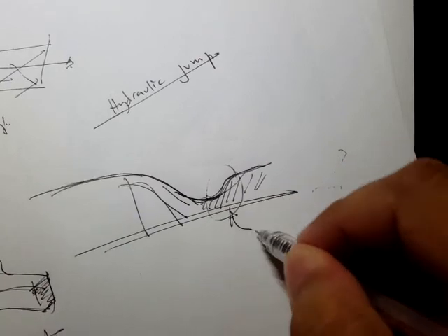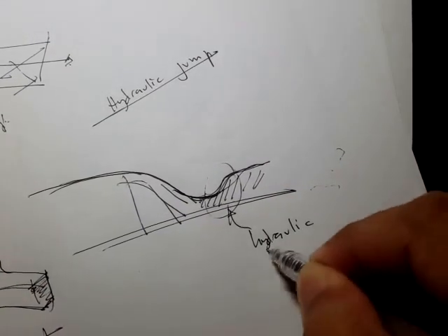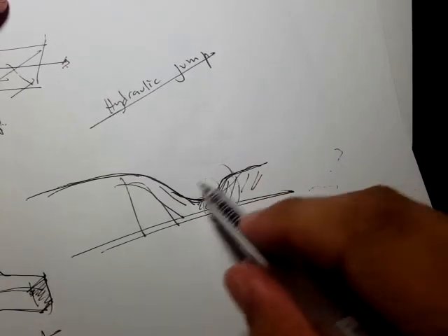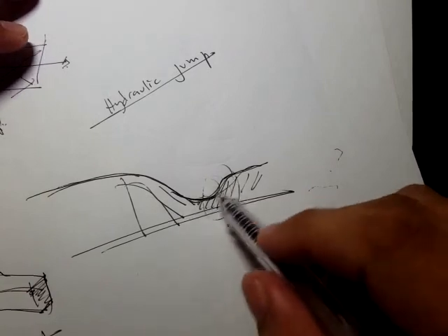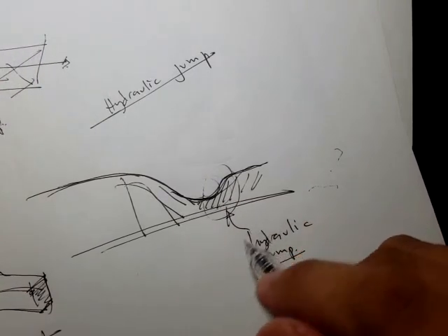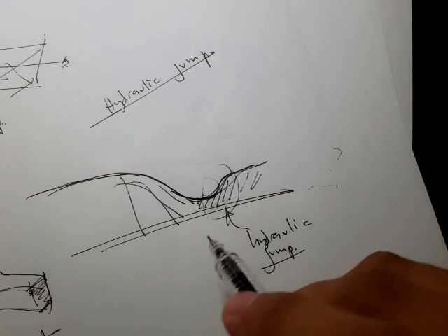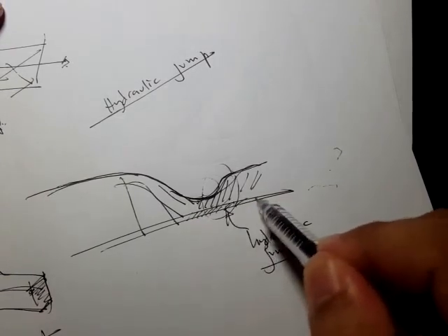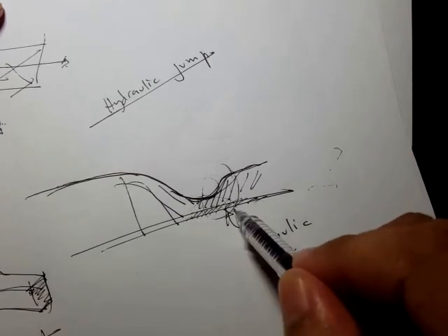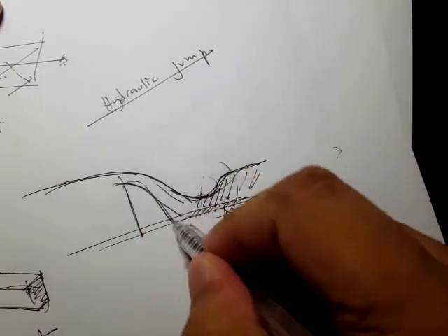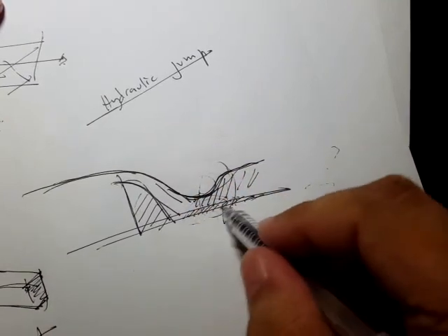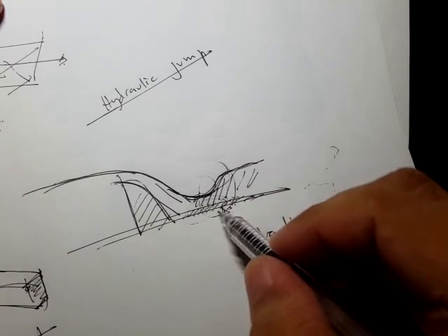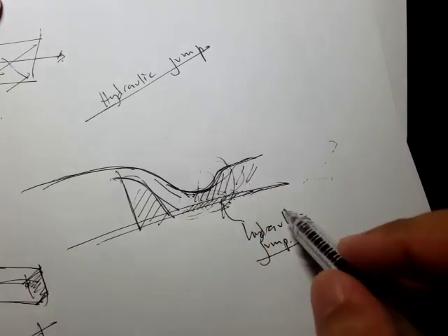So that's what we call the hydraulic jump, and this is associated with energy, because if there's no control for energy in that transition, there's a lot of energy dissipating, and it can damage the soil down here. It can erode, or scar some structures, or cause scouring of the soil near the structure. So it needs to be controlled.